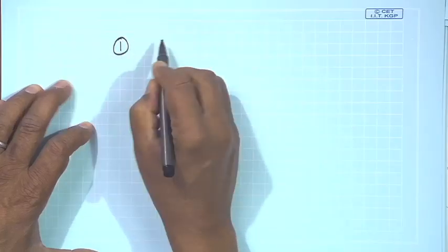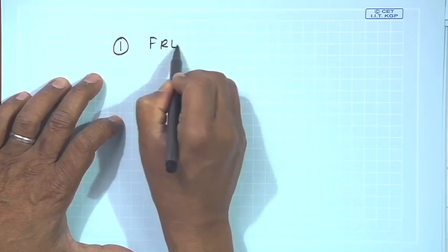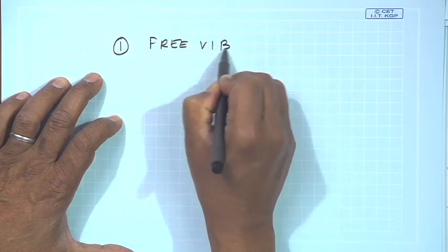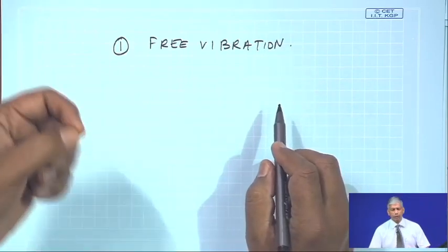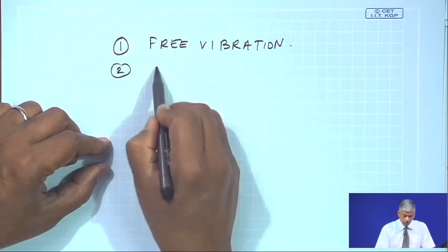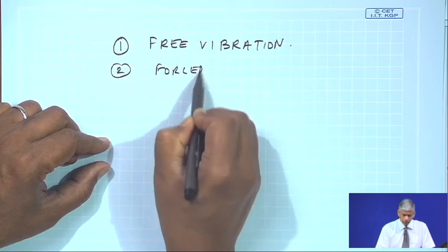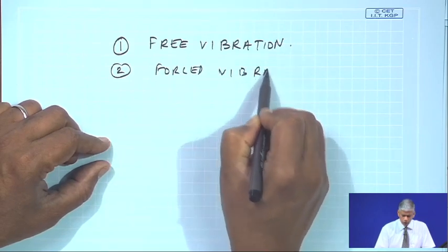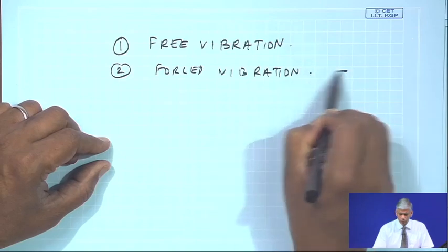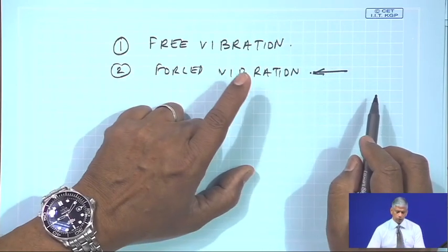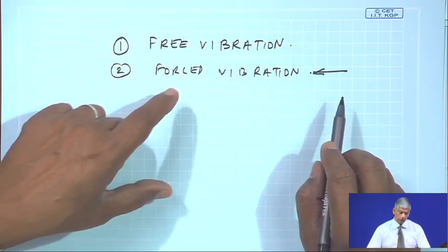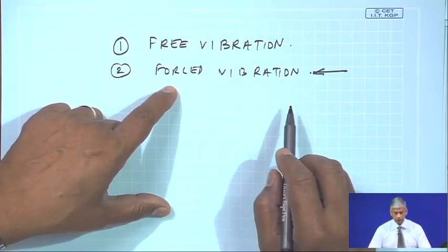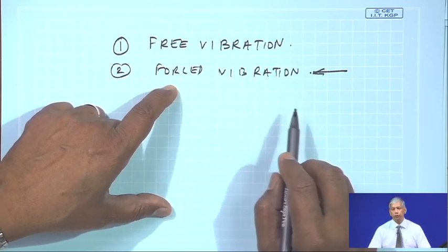Okay. So, as I was telling you, vibrations has many effects, and if I was to list down, one was free vibration. Free vibration occurs when there is no external disturbance or there is an initial disturbance, but it is forced vibration which is giving an energy, because there is an external force, and the frequency of this external force is responsible for making the system run at that external frequency or the forcing frequency.